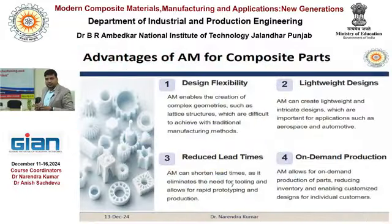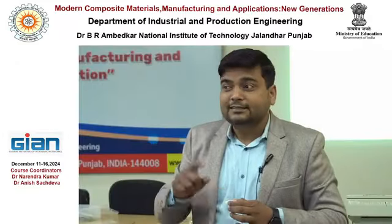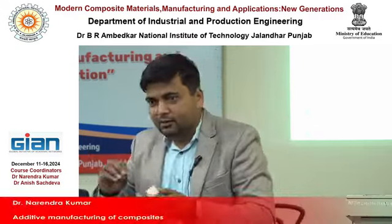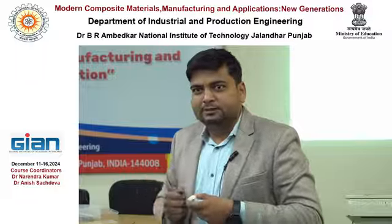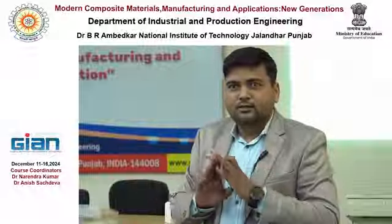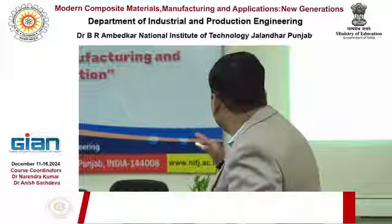Is it true? Can we reduce lead time? How? Yes, because tooling requirements are not there. We are not making any mold. Otherwise, in conventional manufacturing, first we make a mold, so it takes time, 2 days, 3 days, 4 days. But in 3D printing, no tooling is required, no mold is required. So obviously, it will reduce the lead time.